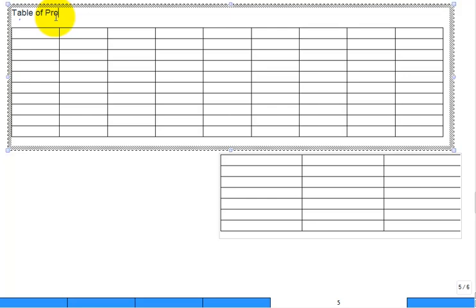And in this table, I like to put a little description to describe the state, and then I have a column for the state numbering, and that's pretty easy. It's like 1 and then 2, etc. But let's go back to that in a minute. And then I'm interested in the pressure as a property in kilopascal. Now I know that some of the pressures are given in kilopascal, sometimes in bars, sometimes in megapascal.